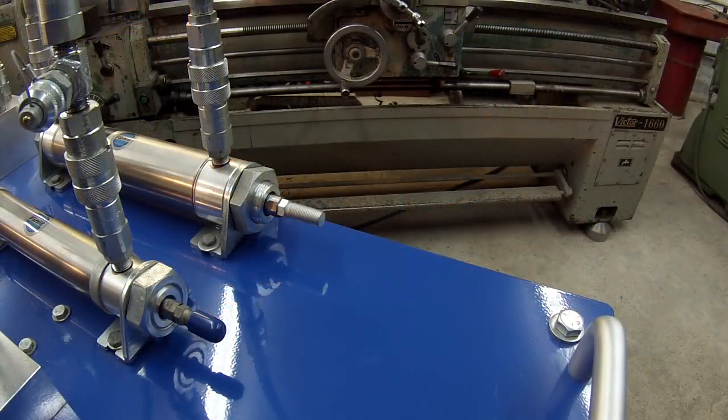One of the fundamental things of all of hydraulics is flow is speed and pressure is force. So what we're going to do now is prove to you that flow is speed. We're going to time this cylinder coming out at a certain rate of flow, and then we're going to cut that in half and show you that it slows it down. So that'll be pretty evident whenever you see that coming out.